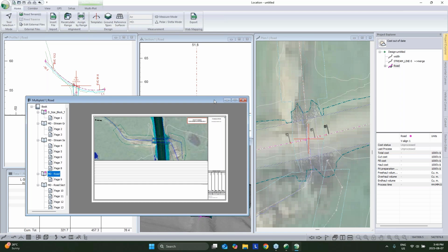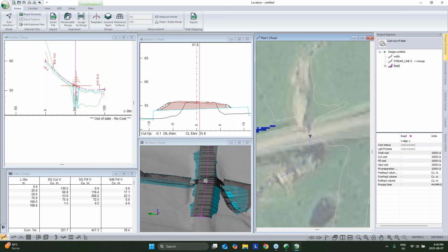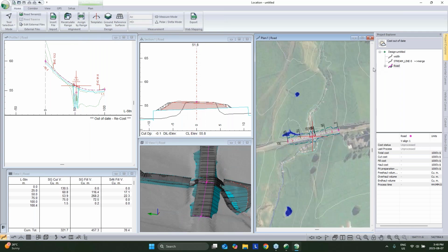So I think that's kind of the high points, and a few key takeaways, just because there is more clicking around for that than a simple example. But for major culverts, usually we're tackling the stream as its own alignment and applying a template to that to represent any kind of earthworks we're doing in the stream and to account for our structure itself.